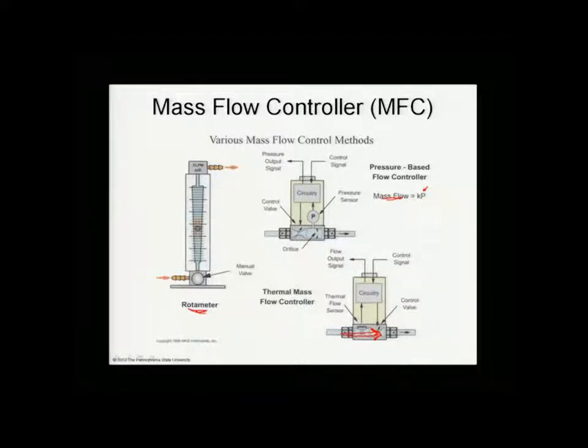So it's important to define the chamber with the vacuum. You create a base pressure, that is, you pump down to a certain pressure in the high vacuum range generally, maybe the ultra-high vacuum range, a very well-defined environment, and then you introduce gases and you control that introduction with these mass flow controller type of instruments.